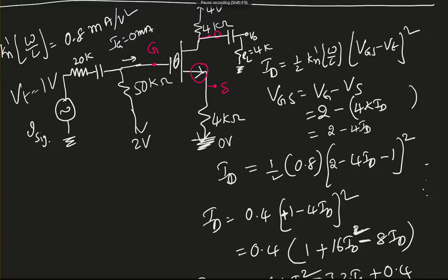Here is the next example of MOSFET. Here we are doing AC analysis in this example. So based on the basic knowledge we have gained from the DC analysis, we know that as long as the arrow is going out, that is an N channel MOSFET, and the arrow is always on the source side, and gate and drain. Okay, and we know that there won't be any current passing through the gate because this is always insulated. I mean, there is an insulation between these two plates.